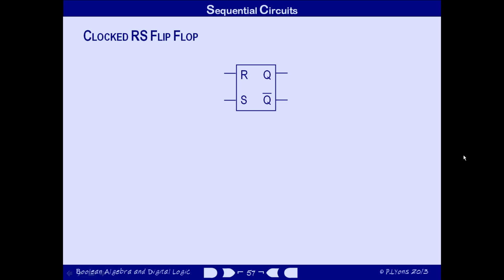So, at long last, let's start building the circuit for a clocked RS flip-flop. It incorporates the circuit we've seen already, and there's a clock signal that enables a couple of data inputs to get through to the R and S inputs of the flip-flop. Now, this way of thinking about AND gates is something that we haven't encountered before. Previously, we've been able to treat the inputs to an AND gate as a couple of indistinguishable bits of data. Now, however, we're looking on one input, the clock input, as a control signal, and the other input as the data.